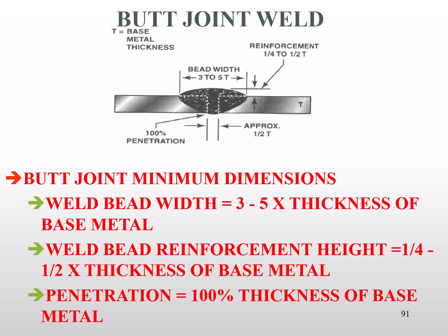And as you can see by this illustration, the weld in the darker color is not only the same thickness of the material, but it actually rises above the material. That's why we need the filler rods to put some extra metal there. And if you'll notice, it's 3 to 5T. Well, T stands for thickness of the material. So if we're running 1/8 inch thickness material, our weld bead should be at least 3/8 of an inch wide.